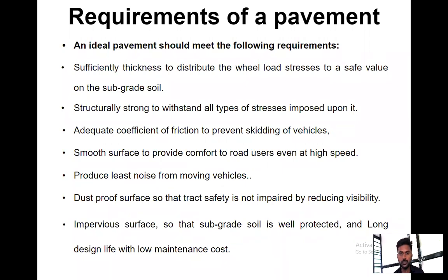If there is accumulation of water, then ultimately by the loads, that water will enter into the subgrade and also affect the bearing capacity. So we have to protect our surface with an impervious surface, so that the subgrade soil is well protected, with long design life and low maintenance. If the pavement is in very good condition, then we need not go for maintenance. If it is not good, then we have to go for maintenance rigorously.